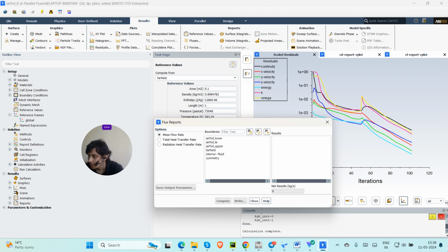There are no distinct inlets and outlets in this problem, just the far field boundary. It would be negligent to simply decide that 0.002 kg per second must be okay because it looks like a small number. The extent of the computation domain in the y direction is 60 meter, as seen to the left. A better way to evaluate the imbalance is to use the boundary values for density equal to 0.9 kg per meter cube and velocity equal to 240 meter per second. The origin of these values is shown in slide 25.